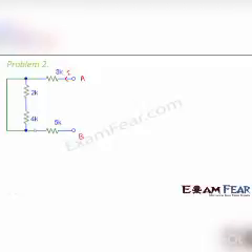So what do you think? Which path will current prefer? Current will prefer to move through this path because there is no resistance along this path. So the entire current will flow through this path and there will be no current flowing through the other path. Since no current flows through this path, these two resistances don't play any role. So the current flows through this 3K resistance and then it flows through the 5K resistance.